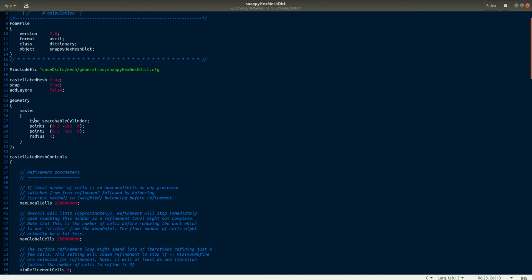It's the cylinder which will delimit the inner portion of the mesh with respect to the outer portion of the mesh. And it's crossing the mesh entirely. You see that the y is minus 1000 and plus 1000. So we can call it watertight, which means that it splits the mesh in two regions which are not connected. If you put fluid in one region, the fluid will stay there and will not go into the other region.